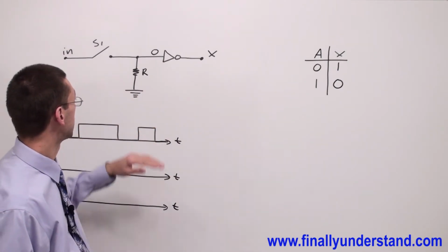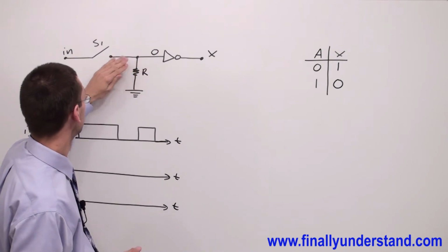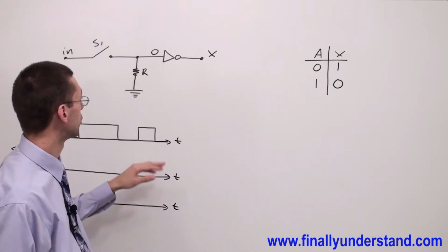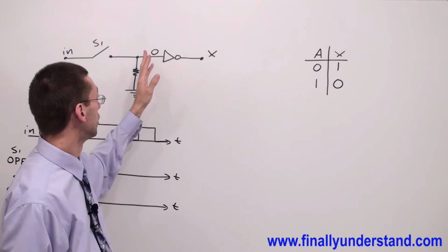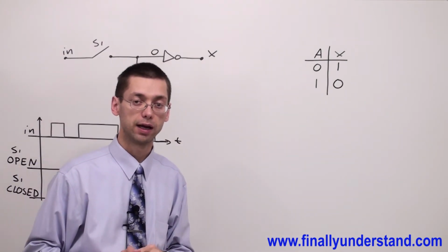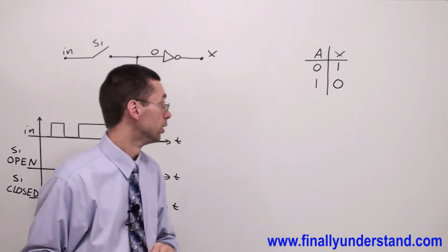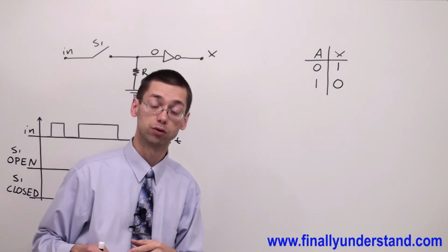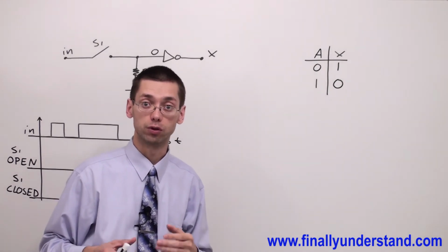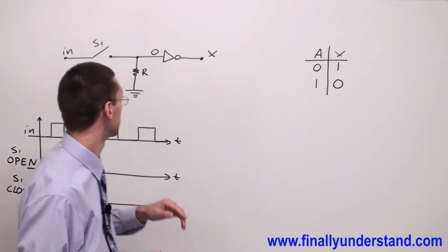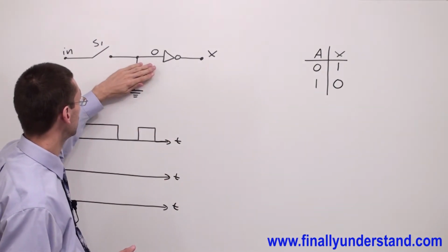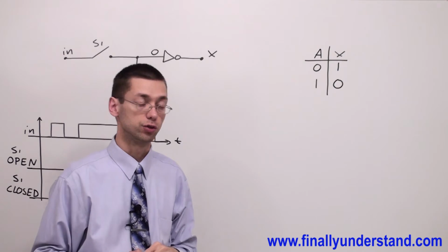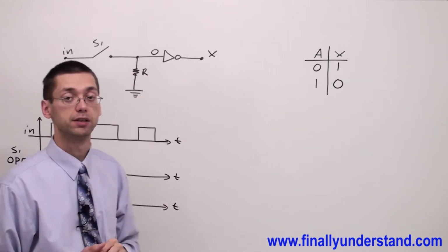And you cannot have a situation where there is no resistance and you have simply a switch, because when the switch is open, you are going to create errors at the output. The input of every gate which you are going to analyze has to be connected to a pull-down resistor or pull-up resistor, to ground or to VCC, or to the output of another gate. You cannot have the situation that the switch is open and there is no pull-up or pull-down resistance connected to the input of the inverter in this case.